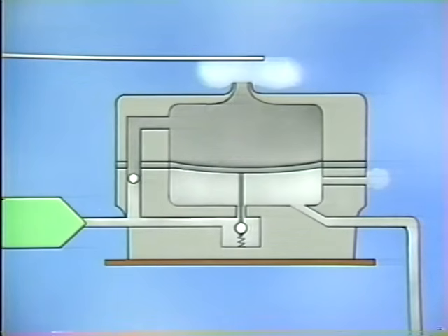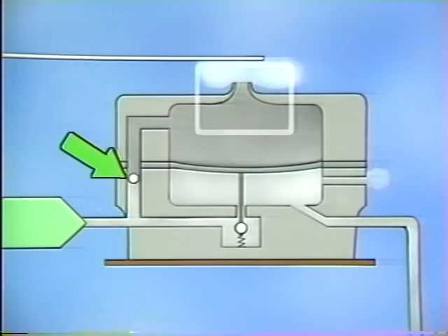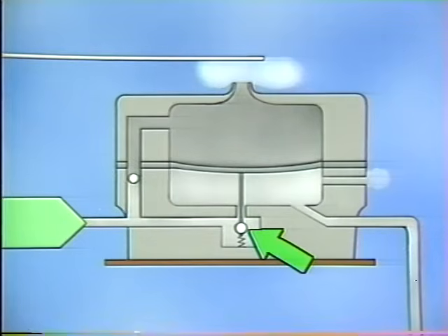You can see that the relay is divided into two compartments by a diaphragm. Air is supplied to both compartments, but the airflow path to the upper compartment includes a restriction that limits the volume of air flowing to the nozzle. The airflow path to the lower compartment has a variable restriction, like the valve plug we saw when we looked at the pilot valve error detector.